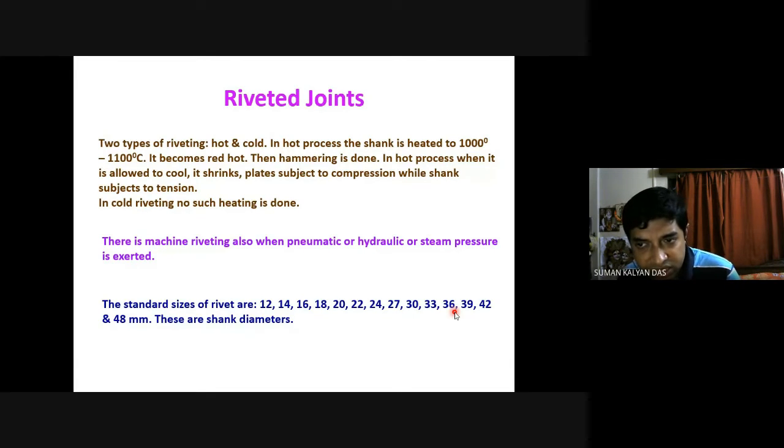Mostly you need not remember them in the exam. You need to select from the standard series, and this standard series will be given, so no need to memorize it. However, having a look at the series, it is not very hard to memorize. 12, 14, 16, 18, 22, so up to 24 there is a 2 mm gap, then there is a 3 mm gap, and after 42 there is a 6 mm gap.